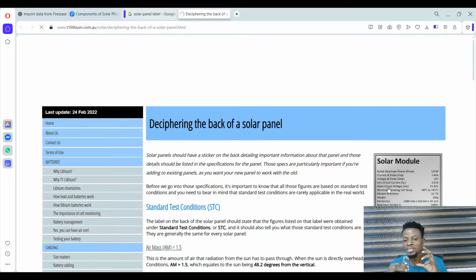You have that spark because at that moment a large amount of, as a matter of fact, infinite amount of current is trying to flow through that short circuiting system. That is why you hear that, and it can even cause fire, because up to 1,000 or 2,000 amps flow in that short circuit. So that is exactly what this is trying to explain to us, the short circuit current.